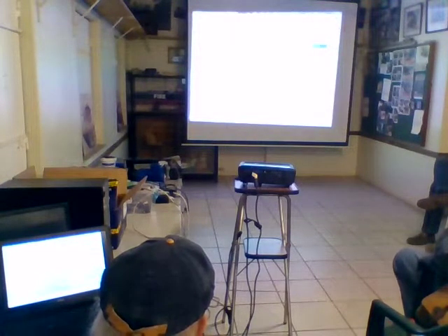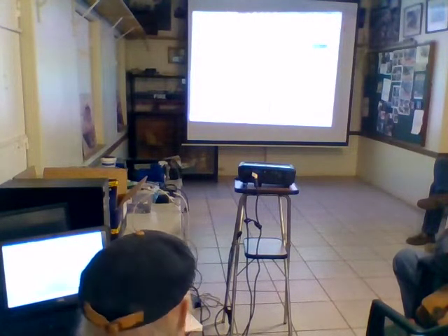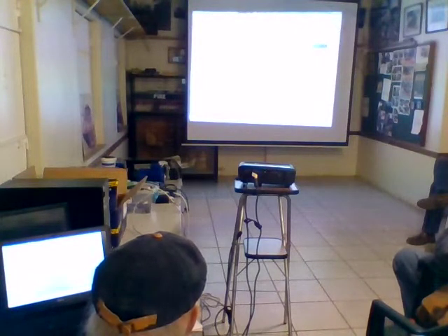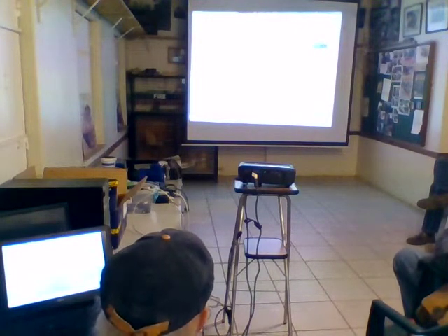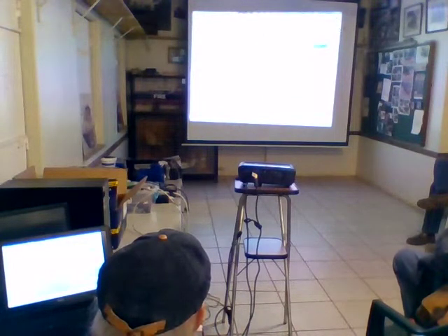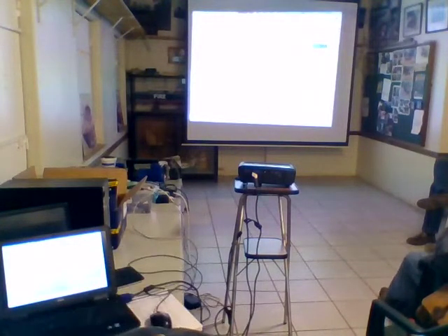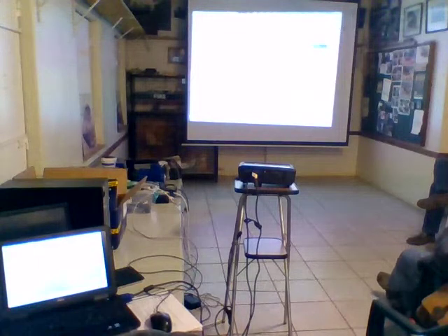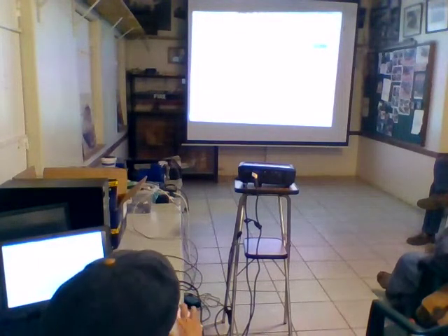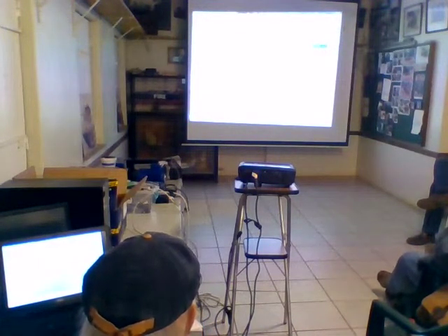See, the linear guide only supplies lateral support. It does not give you any support in this direction. That all comes from the rear here. Now I've got a bit of flexibility that I'm working on here at the back. I didn't model that very accurately. So if you're cutting on one edge and you apply the Y on one edge, that's going to be quite severe. You're applying the Y almost on the linear guide now. Oh, sorry, on the lead screw now.